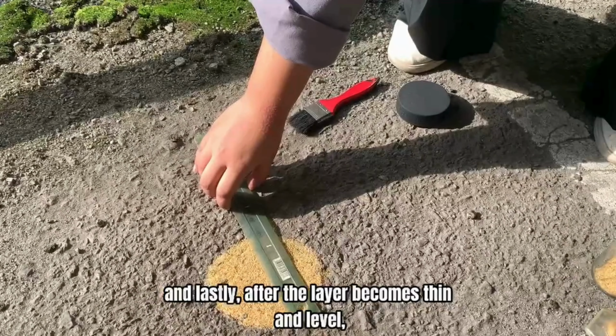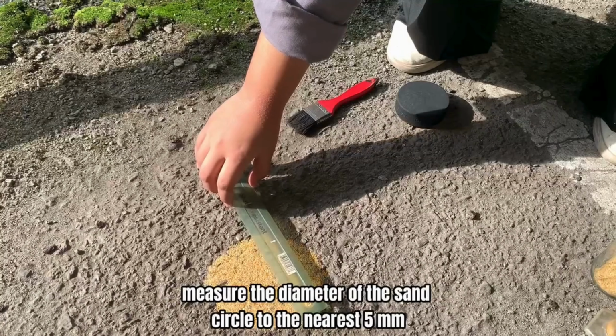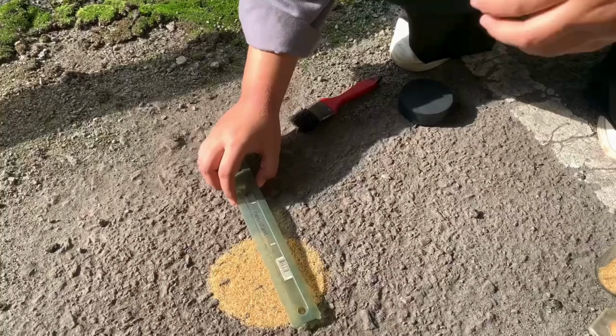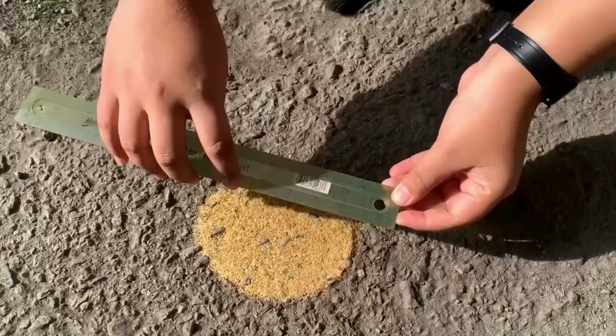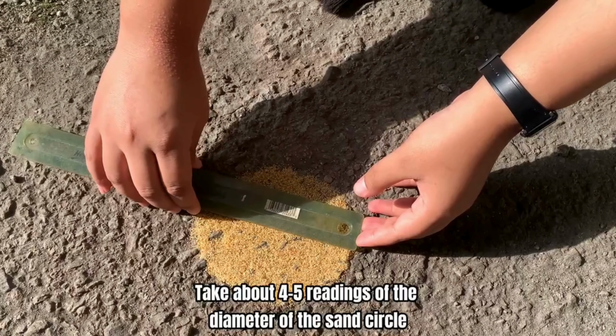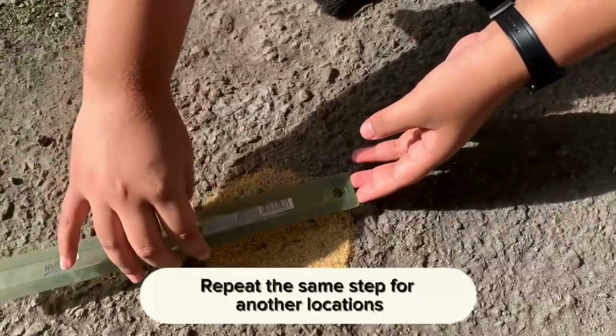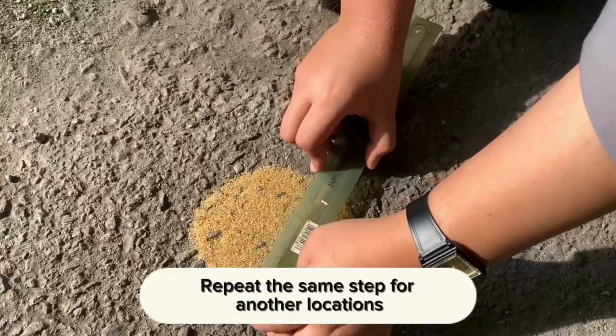After the layer becomes thin and level, measure the diameter of the sand circle to the nearest 5 mm and record these measurements. Take about 4 to 5 readings of the diameter of the sand circle and take the average. Repeat the same step for other locations.